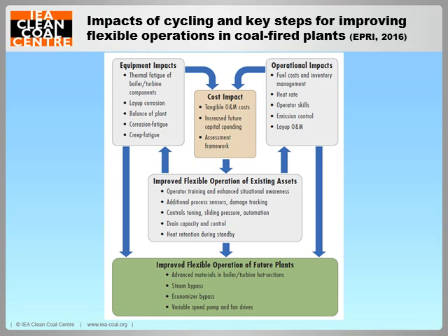The flexibility capabilities of modern advanced coal-fired power plants include startup times of 1 to 4 hours, down from 2 to 6 hours, and minimum load reduction capability from 40% down to 25% and even lower. In addition, if indirect firing is used and improved, primary frequency control times can go from 2 to 5% within 30 seconds to 10% within 10 seconds.